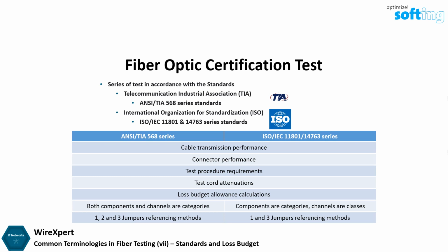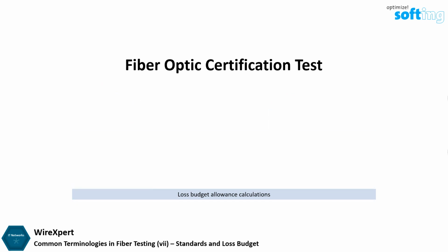When performing a fiber optic cables test based on either of the standards, insertion loss test is done to compare with the calculated loss budget of the installation.